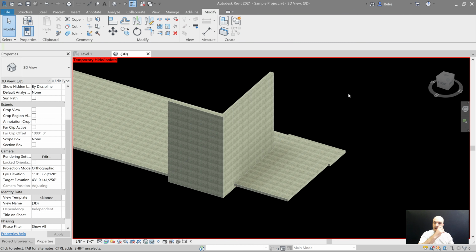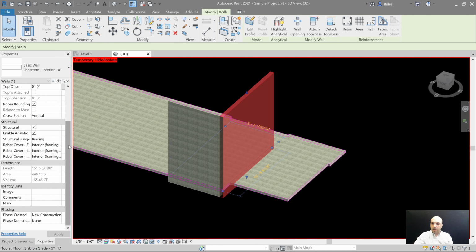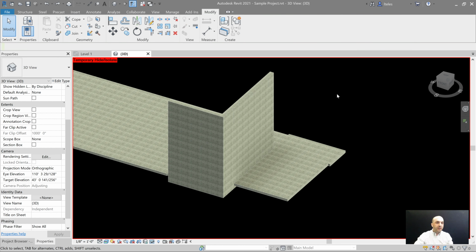So now in Revit, I'm going to do an undo, Control Z. And now you can see that my floor is slicing through my wall again. If I select my wall and go back to my numbers, I got 165.46. You see how the numbers changed? So it's very important that as you think about construction and how something is actually going to go together, you're communicating in Revit, and Revit's communicating back, letting you know, okay, these are the numbers that I came up with. You don't have to worry about the numbers. You just worry about the construction.